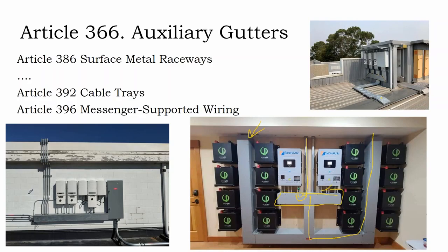I can't really tell if they're plastic or metal from here. Well, if you use gutters or cable trays, then you're making this run relatively simple. There are parts in cable trays for flexibility, and then you can just walk through and lay in and line the cable into it. So the actual cable run itself is substantially faster.